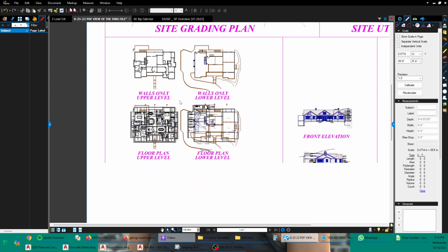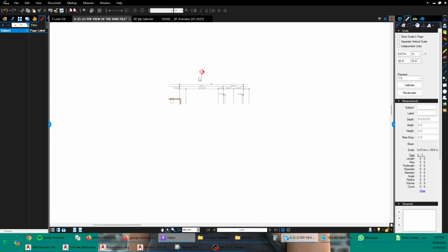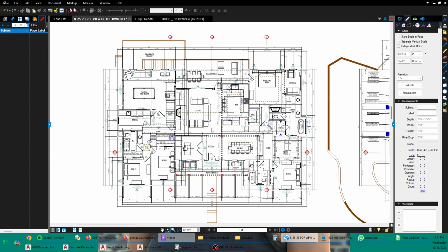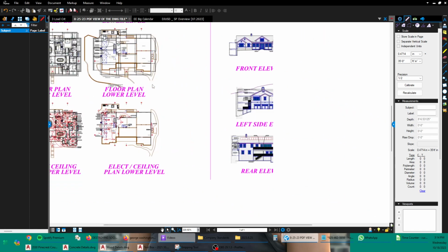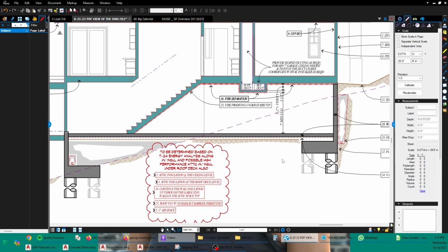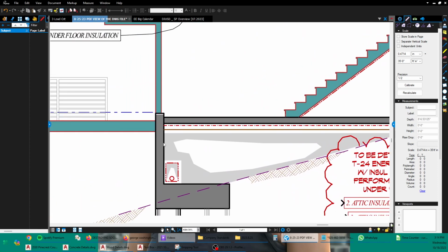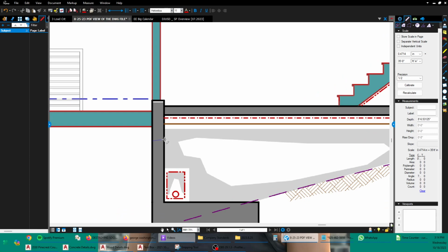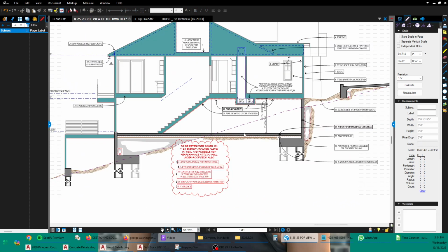Here we go. These are section detail callouts. Is there one that goes right through the thing I'm trying to draw? We could check this one maybe, 2 on A11. Here. So what I see here is retaining wall, 8-inch thick retaining wall, concrete retaining wall.